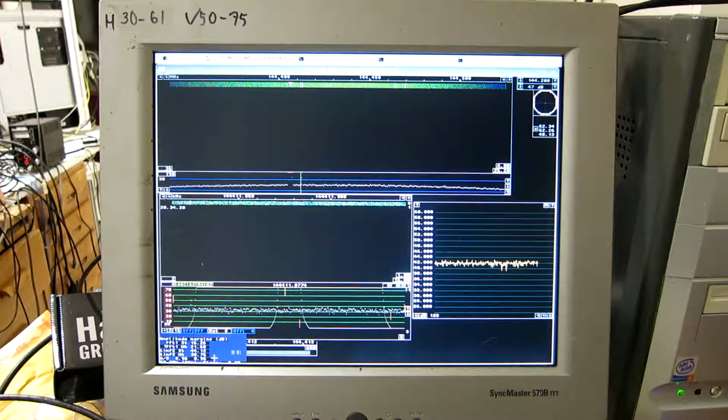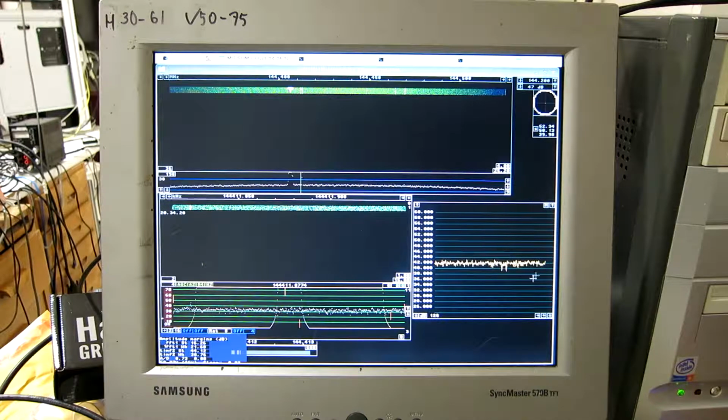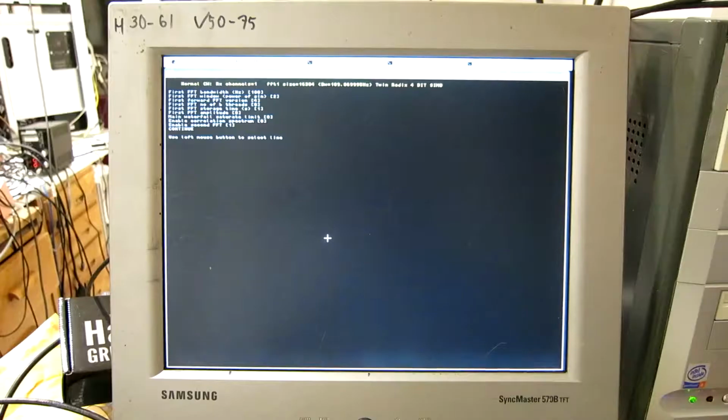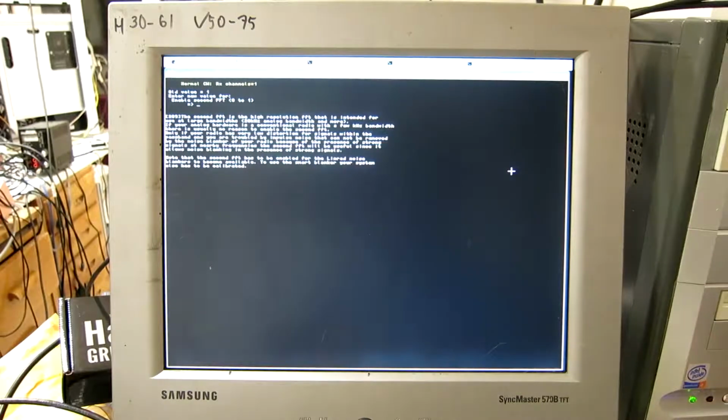And now it's 1 dB below saturation. And the frequency separation is small, but the noise floor did not change. It's easier to remove the second FFT when measuring signal to noise for a strong signal. So I make this 0.